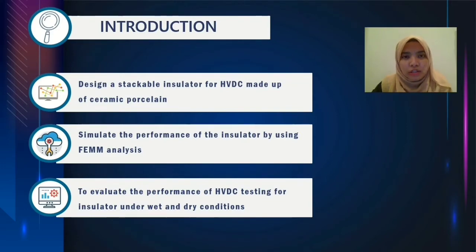For most countries in Europe and also in Malaysia, we follow the IEC 60071 standard, which is insulation coordination. The standard we strictly follow because before the equipment such as the installation of the transformer is able to operate in its service, we need to know its capability to withstand the abnormal and normal condition of the high voltage.